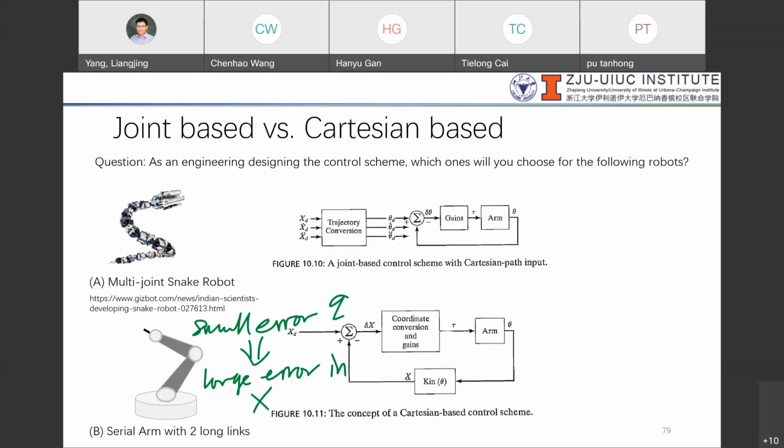The best thing is if you just put a sensor here and measure Q, and after that you calculate X. It will actually result in a larger error than if you use a camera, or any other tracking system, to get X, which gives you a more accurate measurement.